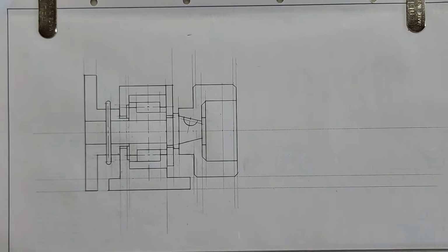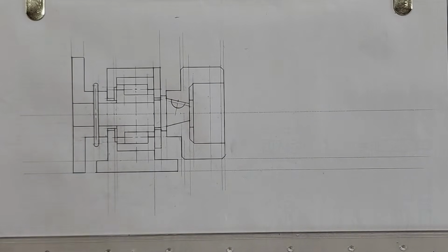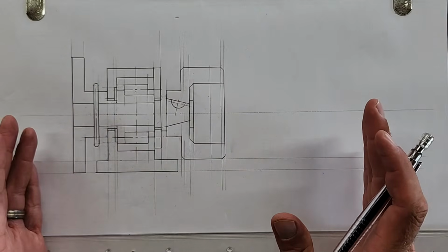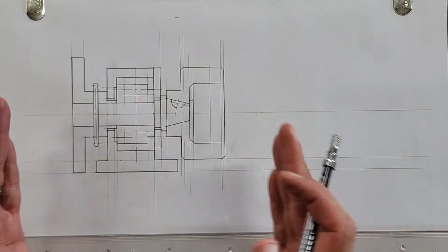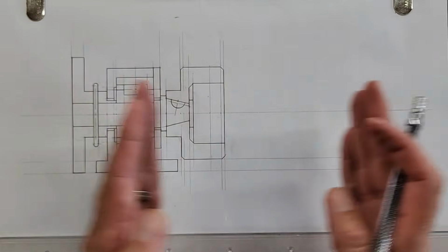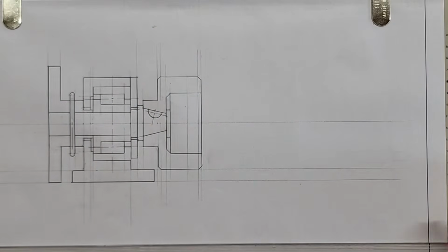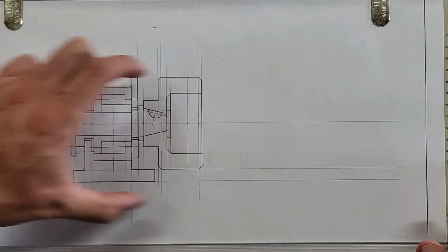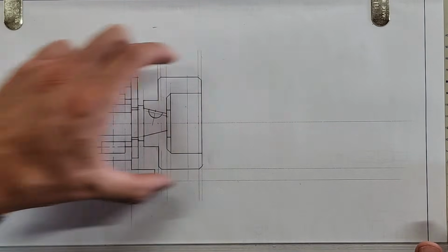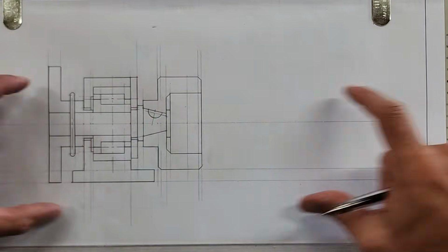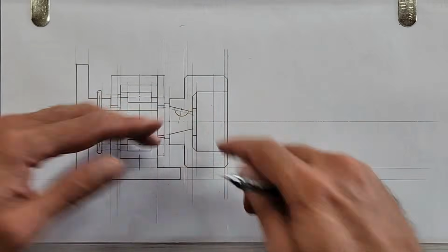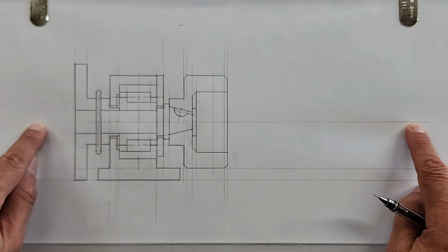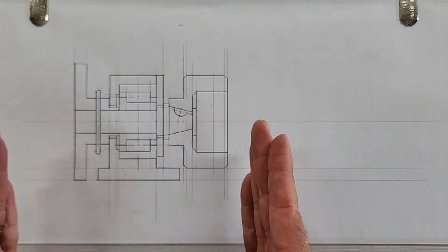Now I've started it off because we don't have 90 minutes in this lesson. I'm going to just talk you through how to get this done and then hopefully finish this with you. So we wanted the front view with a right view. Planning is going to be important. Determine what is your maximum height, and in this case it was 100. Spacing wise, nicely spaced in the middle of my page, height wise, that's going to be fine. So I started with that construction line, which is eventually going to be a center line.